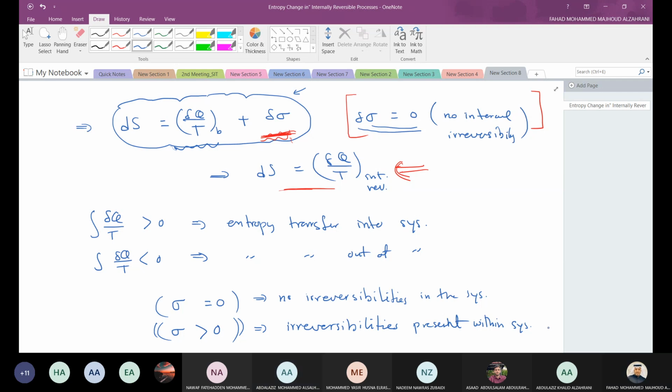I don't remember. Go back to the question. It was evaporation, right? Starting from saturated liquid up to saturated vapor. And the piston was freely moving. During phase change, always go back to the original concept. Don't assume things or connect things that are not relevant. We have phase change, and with a freely moving piston, that means it happens at constant temperature and pressure. That's why it's constant temperature and pressure. It has nothing to do with the internal reversibility. Okay, thank you.